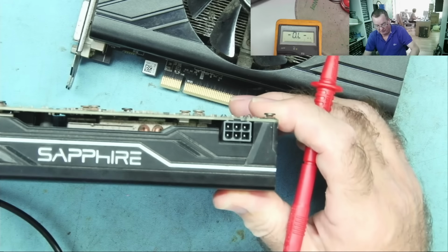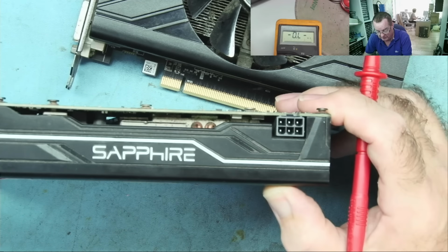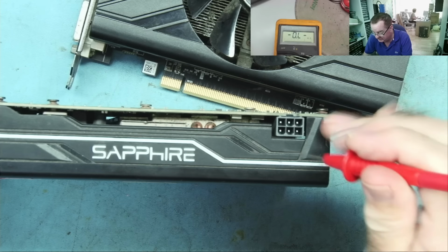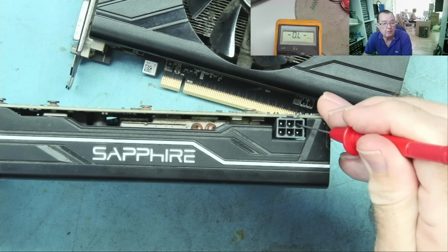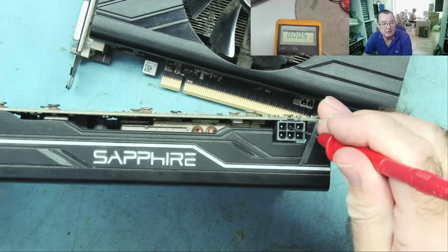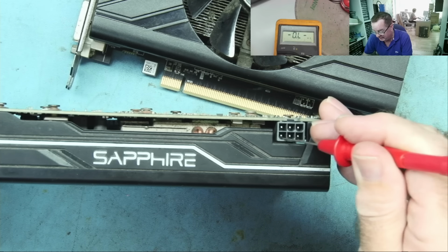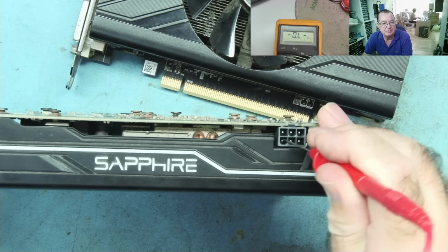And again, with this one, we can just check for any shorts or low resistances on the 12 volt in. So again, I'll just go to ground, which is the bracket. And let's have a look. What's the ground side of it? Yeah, so these will all read 0 ohms basically, and these were reading in kilo ohms or tens of kilo ohms on the other one.